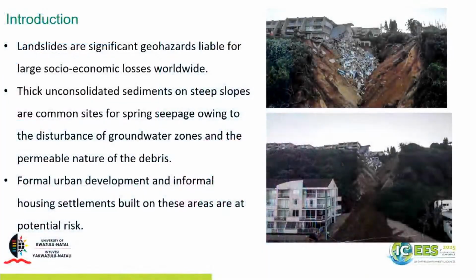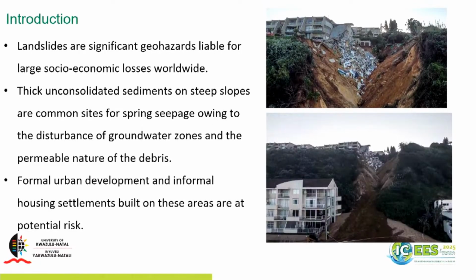Landslides are significant geohazards which are liable for socioeconomic losses worldwide. As you can see from the two figures on the right, these are landslides that occurred in Durban during the flood period. Thick unconsolidated sediments on steep slopes are common sites for spring seepage owing to the disturbance of groundwater zones and the permeable nature of the debris. So when you have formal urban development and informal housing settlements built on these areas, they are areas of potential risk.